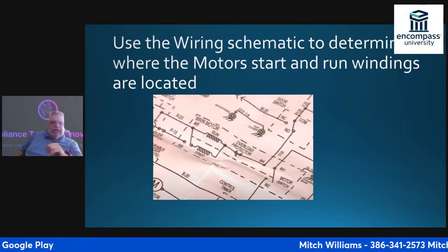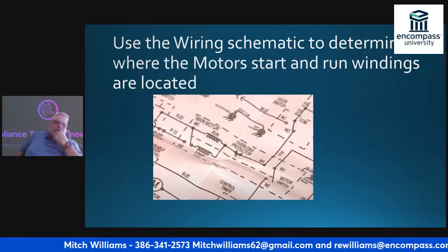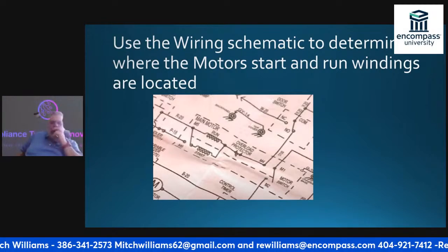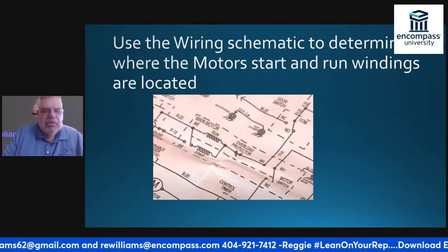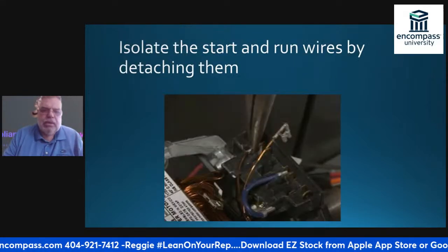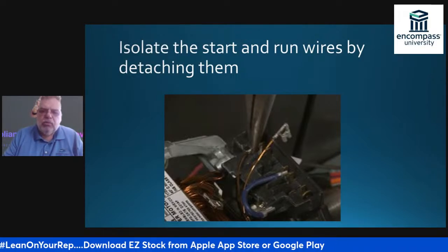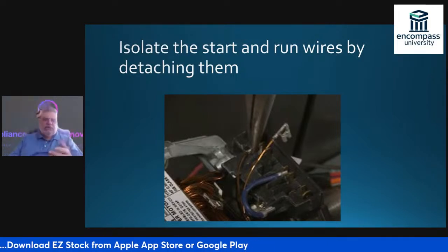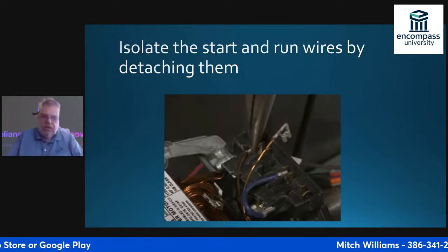Okay, so I have got to make sure that my switch is good. If I know that my switch is good and it checks out, I'm going to move over and check the overload. But let's talk about the run and the start portion of it. I'm going to isolate the run and the start by detaching the two wires that go from the motor to it.